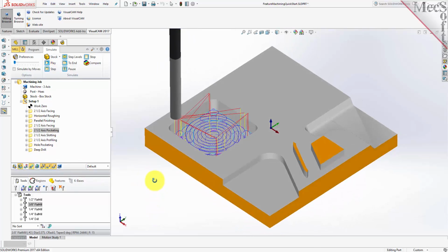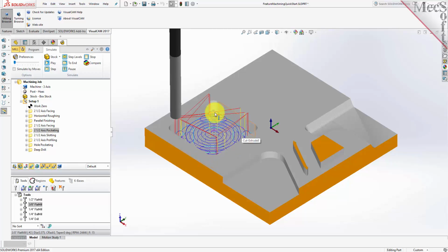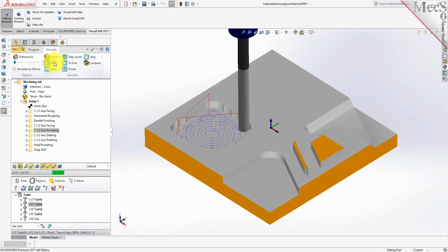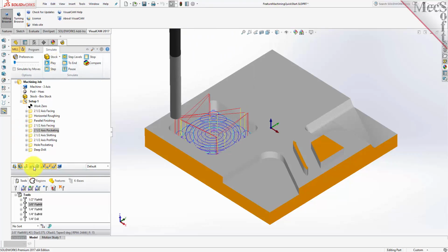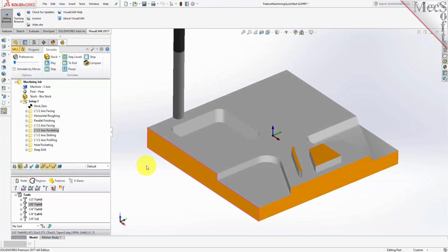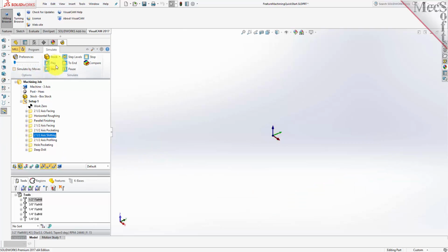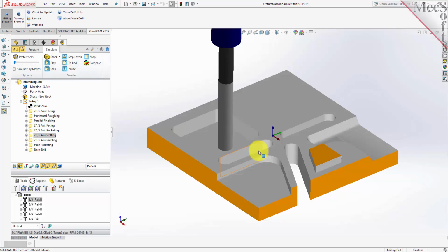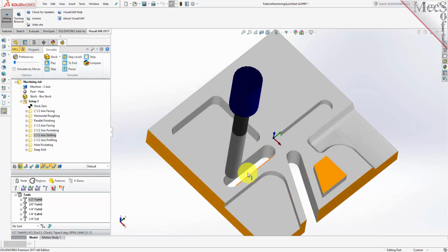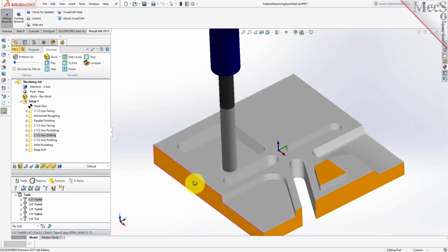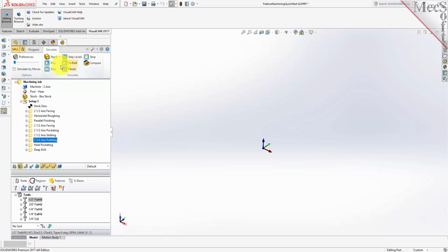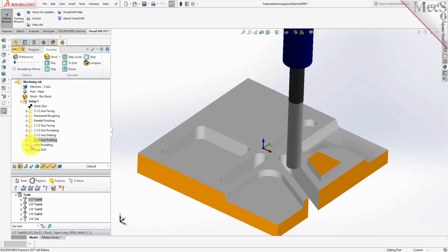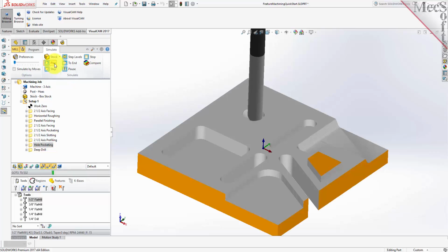High-speed cut pattern has tangential loops in the pattern, so you can run this at a higher feed rate. Let's go ahead and run that again. There's our blind pocket in the front. We'll go on down to our slots, run those. As you can see, it did both through slots and the blind slot at the same time. Let's go ahead and do our profiling operation for our boss. Clean that up. Do our hole pocketing.